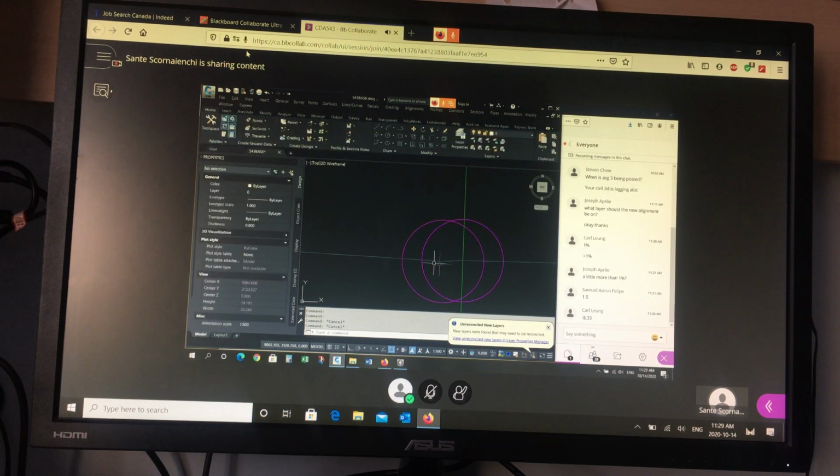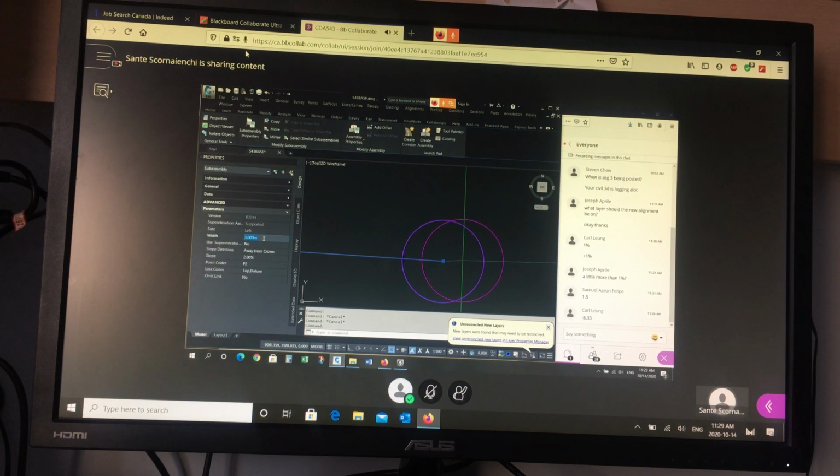The next piece is the face of curb. So this is only 0.05 wide, and it has a 300% slope. So there's the face of curb. The next piece only needs to be 0.15, and it's flat, 0%. And the last piece needs to be 5.55, and it needs to be positive 2%, so it's ready to go.